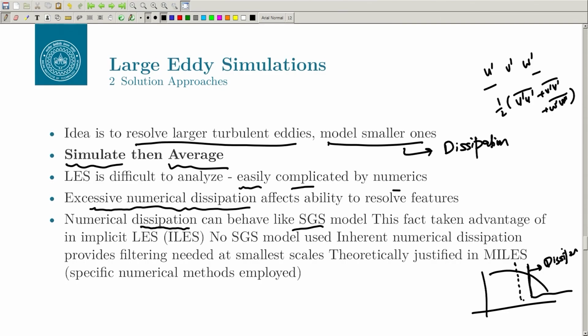And as I discussed in the beginning, there are different ways of doing LES. So, they have WMLES, which is wall model LES, and there is very large LES, VLES, and then there is some hybrid model. WMLES is also a kind of hybrid model. There is WRLES, which is wall resolved LES.